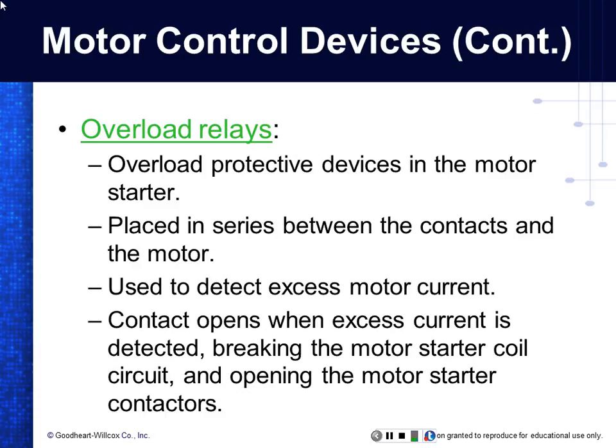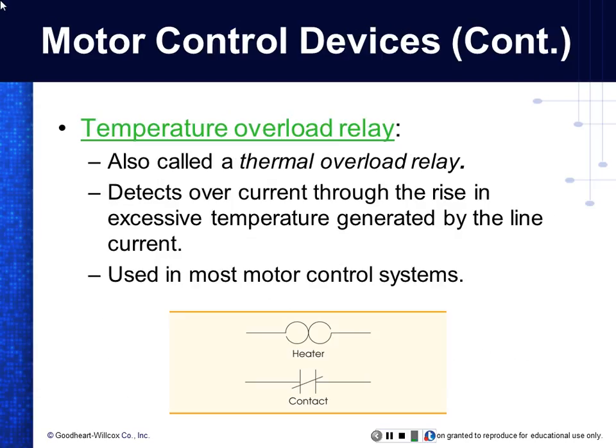Overload contacts. All of the motors have overload contacts, but one thing I am going to tell you is if you've dealt with motor control drawings, we don't put the contactors in a PLC drawing. I mean, the overloads don't go in the PLC drawing because we don't draw the motor. And when we draw the motor starter, we just draw it as one thing, so everything's in it together. We just draw a circle, that's it. There are also temperature overloads. These are the symbols for them.